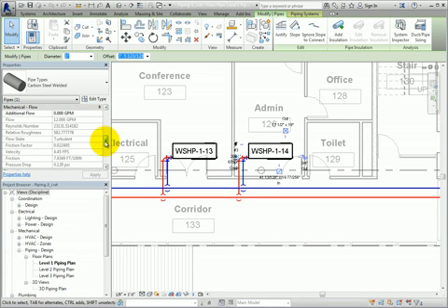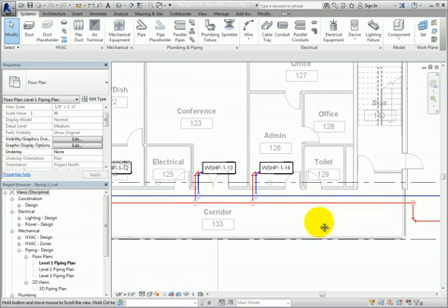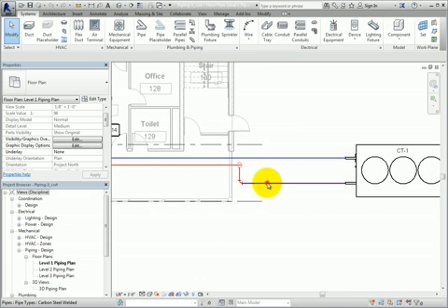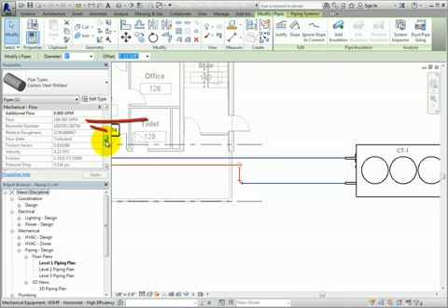Let's begin by sizing some of the condenser water return segments. I will select the horizontal pipe segment connected to the cooling tower. Looking in the Properties palette, I can see that the flow is 168 GPM or 10.64 liters per second in the metric file. There are also a few methods to sizing piping in general, such as by flow, friction, velocity, or some combination of these.